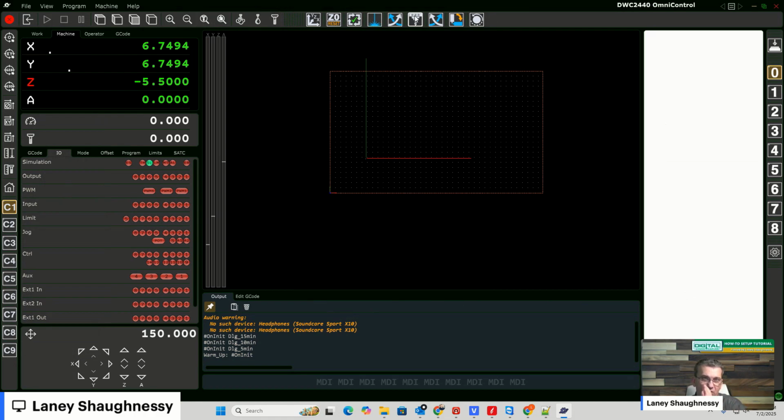Enable spindle mode, which you're commonly known as mill mode. It's now spindle mode. This is when you're running your spindle. Enable laser mode is when you're running your laser. Move the spindle to the laser position.